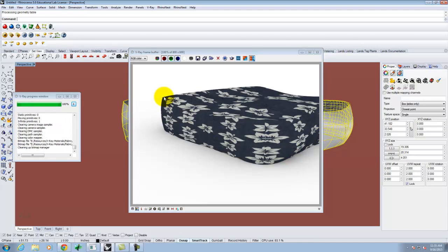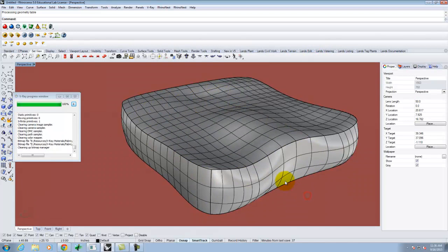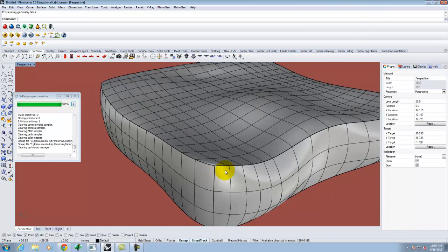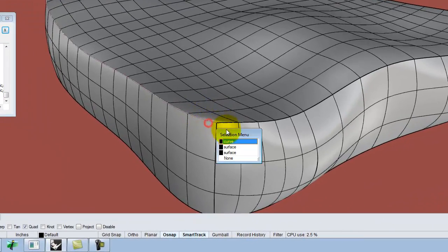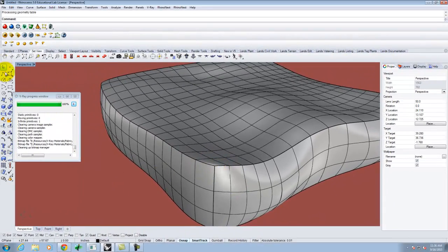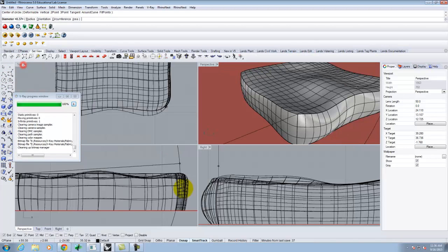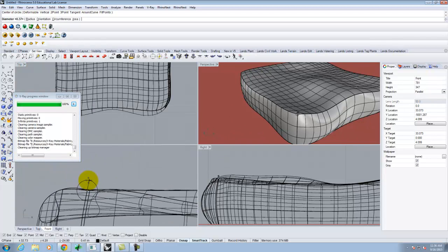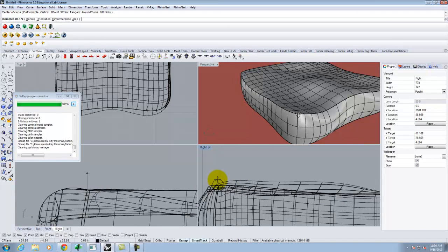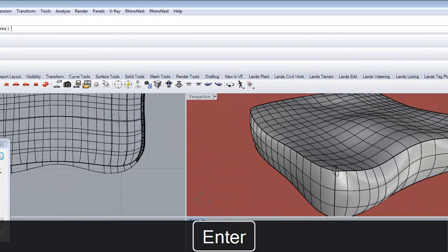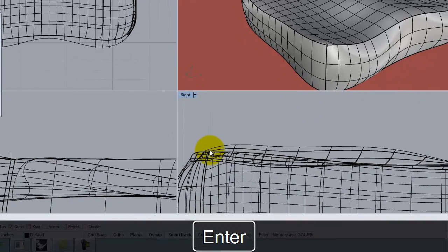Because we've got this hard edge there, I'd like to put a little bit of a trim, little piping around it or something. So let's go ahead and do that. You guys know how to do this. It's just a sweep. I have my curve still, but I need a cross-section curve. So let me create a circle, and I'm going to do it in one of my side views here. Let's do it right here. The diameter is maybe 1/4 inch. It's a little too big. It's like 3/16 or something like that. Okay, there it is.